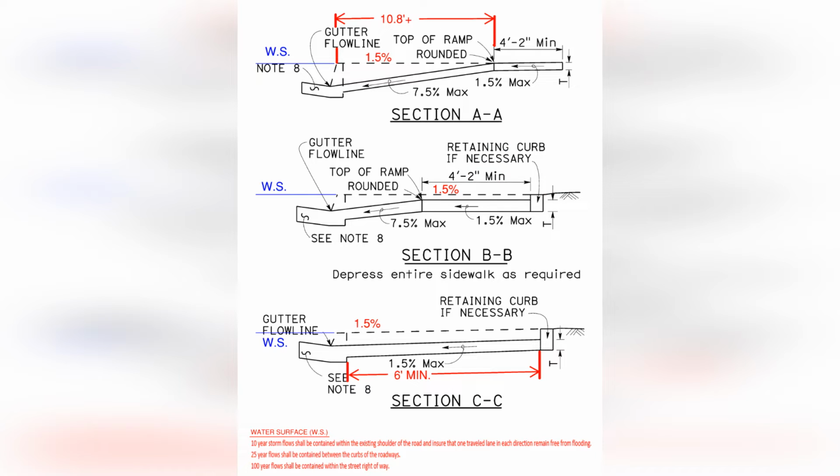Moving down the section to the Caltrans Case C ramp, Section CC. The advantage you will have with this style ramp is requiring less right-of-way for construction. You will sacrifice the water surface elevation, keeping the landing and ramp usable during any type of storm event. You will receive more sediment buildup on a Case C ramp, Section CC. Truthfully, we construct many Case C ramps because it requires no right-of-way, or much less right-of-way than all the other ramps.